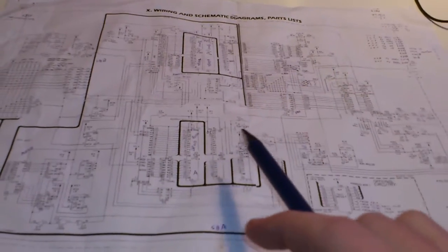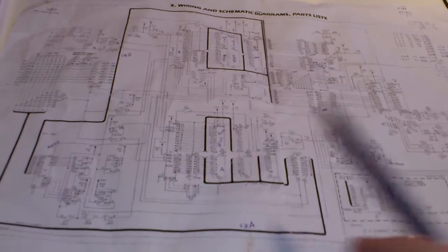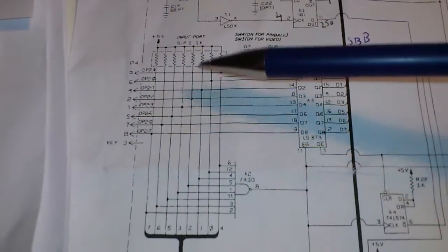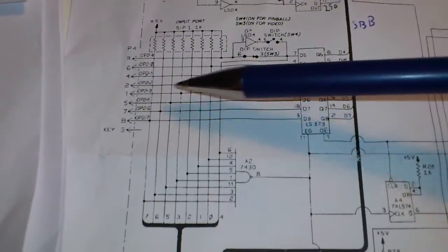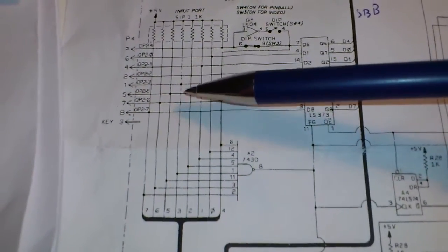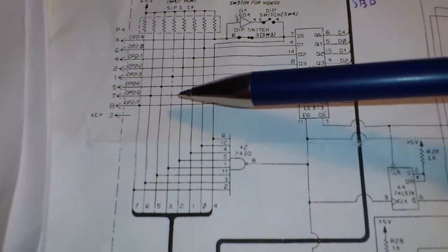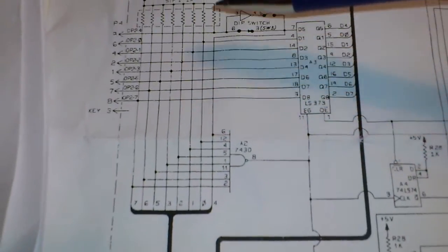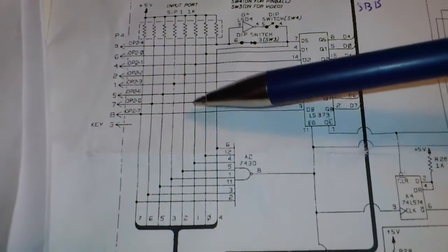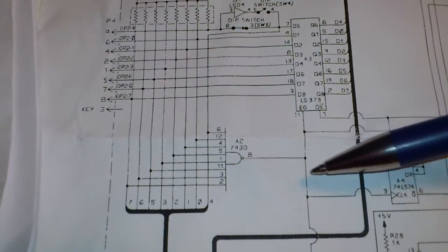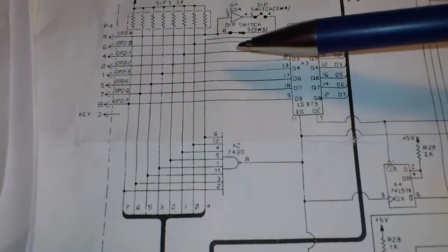Let's start to look into the interfacing logic, the way the video system is communicating sound codes over to these soundboards. Here there are 8 digital lines coming into the soundboards. They're connected back to the video system, and the video system is putting out the sound code, which represents one specific sound to be played by the soundboard. If all those 8 lines are 1, so high, there is basically no strobe coming in here, so that would be 0. That corresponds to the idle sound code.